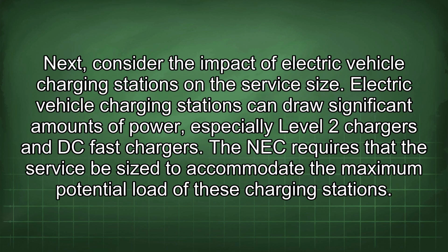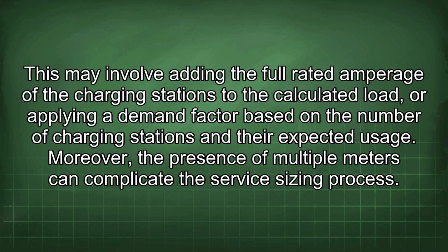Next, consider the impact of electric vehicle charging stations on the service size. Electric vehicle charging stations can draw significant amounts of power, especially level 2 chargers and DC fast chargers. The NEC requires that the service be sized to accommodate the maximum potential load of these charging stations. This may involve adding the full rated amperage of the charging stations to the calculated load, or applying a demand factor based on the number of charging stations and their expected usage.